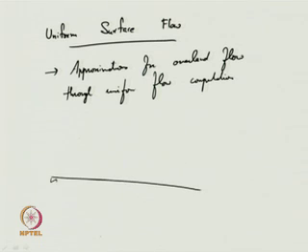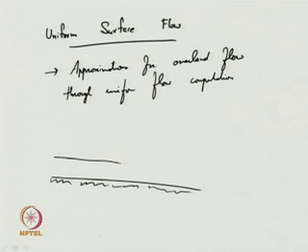Say this is your land surface. When rainfall occurs, after some quantity gets infiltrated, and before the water reaches the main channel or any channel, it flows along the ground in the form of a thin sheet. So this depth is quite small. Let me say this depth is y m, some very small depth, and it may not go beyond this depth; mostly it is very thin.